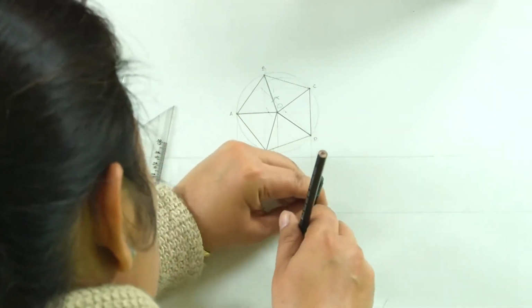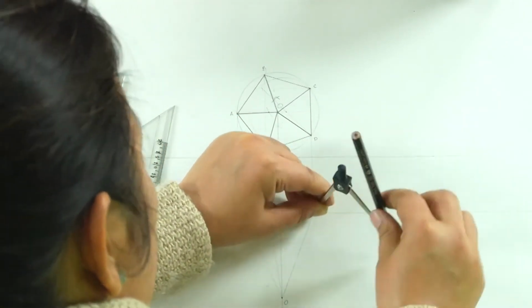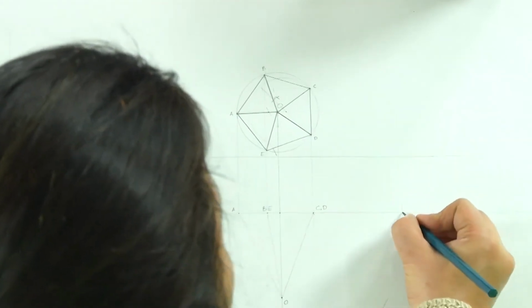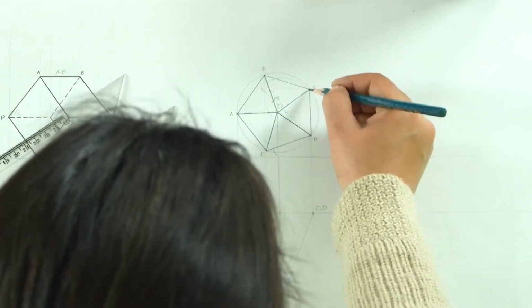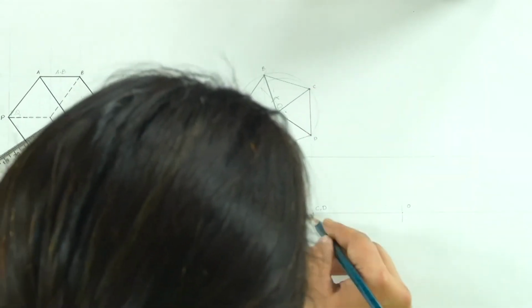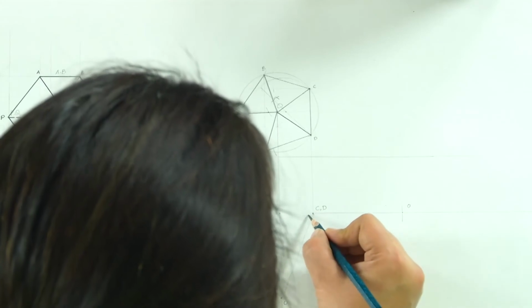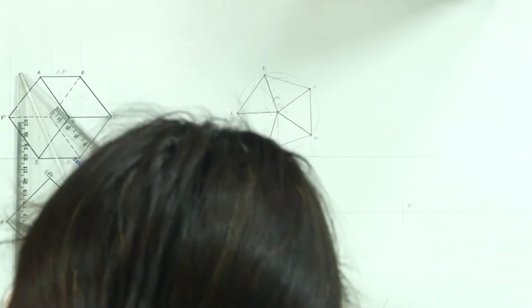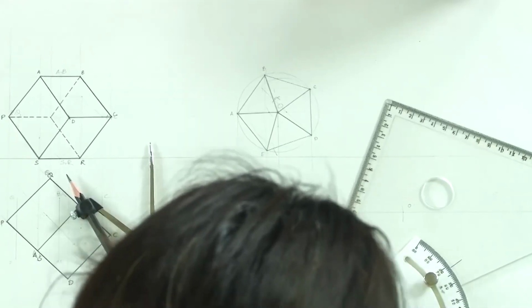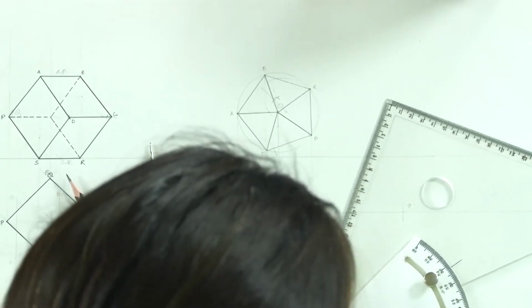We will start to incline. Since CD is the edge about which we are inclining, we first got our apex O here. Now we know that about this line connecting CO, we have this line AC making a certain angle, which is what we will repeat. So if I set my set square about the parallel, which is here, by a certain degrees, this is the angle which this line is making with the horizontal, which is this line.